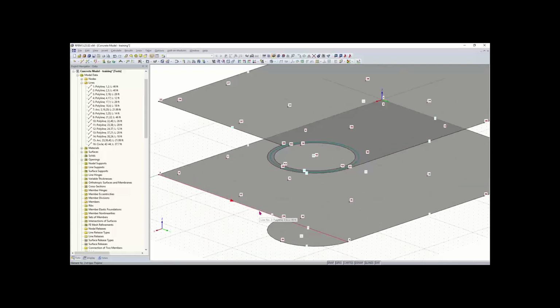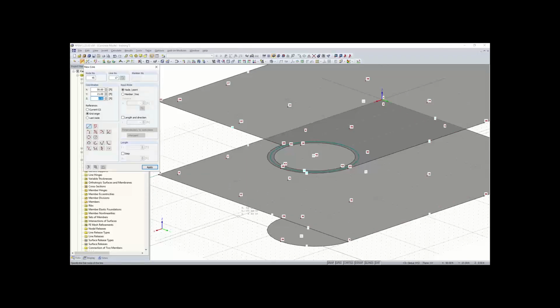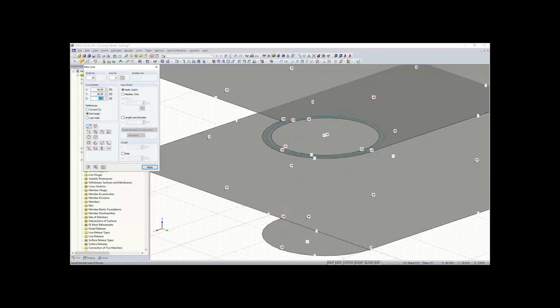Well, I don't need to create a new node there. I can just go up here to new line. And basically what I'm doing is just connecting the floor to the ceiling with this line here, which will act as our wall boundary. And this is going to be about 7 feet away from node 20 here. So that will be at 4619. So we'll go to 4619. I'll draw up to the line, and again, you get that nice symbol there, that snap point for perpendicular, kind of like AutoCAD, and there you go.